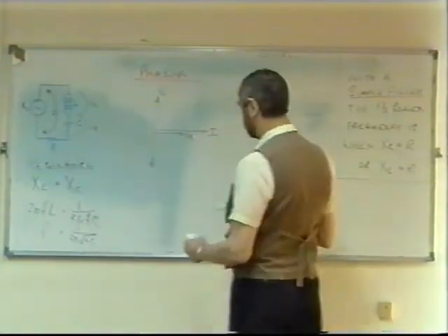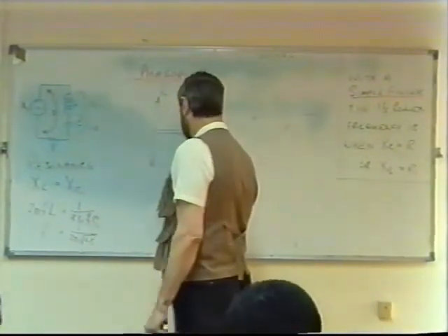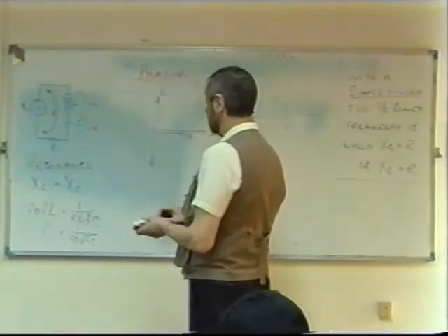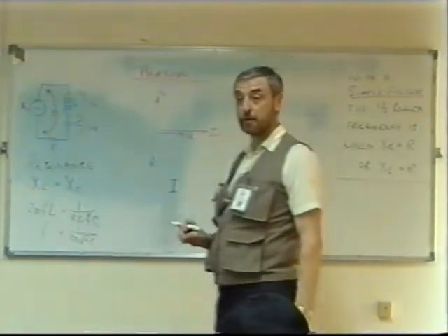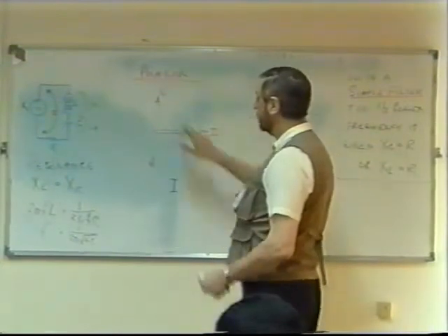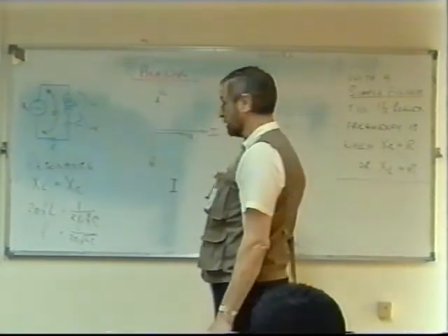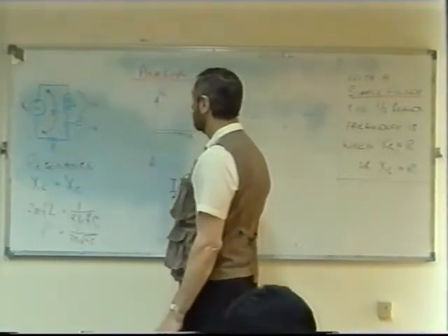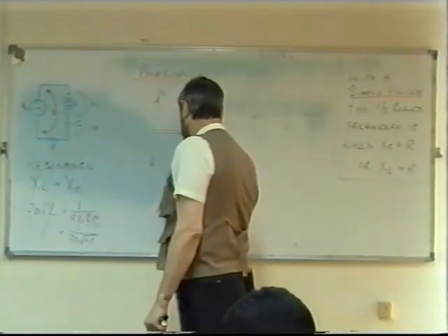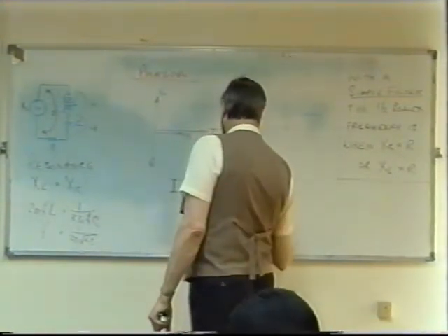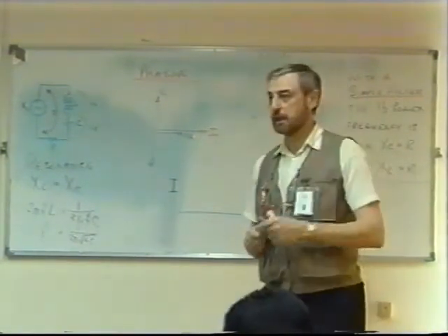That's called resonance. In fact, you can draw here, for example, a graph of the current, in a different colour. This is a phasor diagram. This is a resonant circuit. This is what we're talking about when we say resonance. When can we use it? Well, we'll come to that in a minute. If you're drawing a graph showing the current against frequency, it should become clear what's happening.